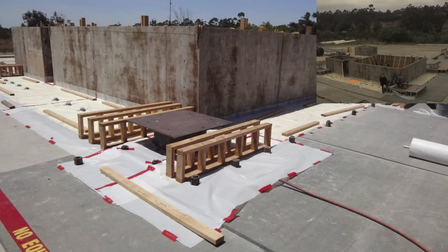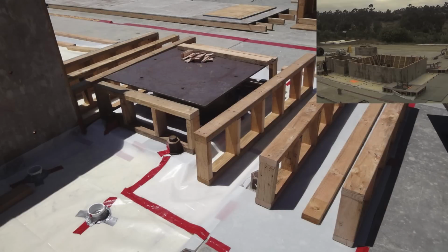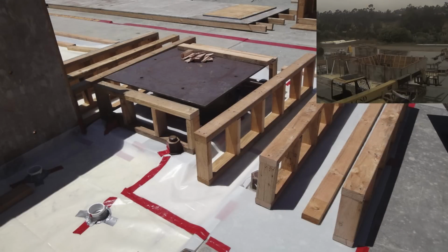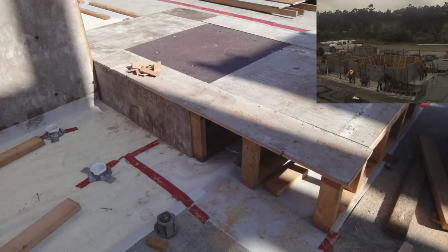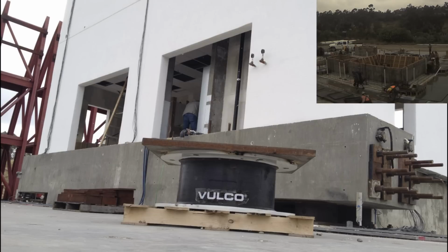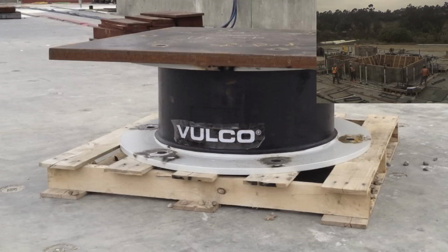After completion of the interior formwork, the exterior formwork of the foundation is constructed. Unlike traditional building construction, in the 5-storey building test box, elements were fabricated at each corner of the foundation to prevent the concrete from filling in the spaces where base isolators would eventually be installed. Base isolators are sometimes used in regions of the world where significant seismic activity can be expected, such as the west coast of the United States. When properly designed, a building supported on base isolators will observe much lower seismic forces and displacements than compared to a building fixed at its base.